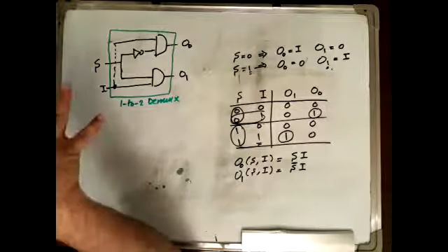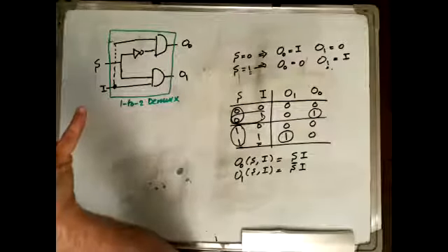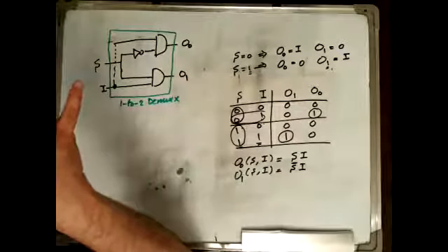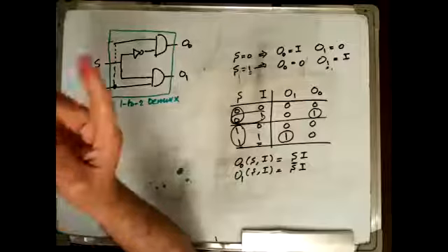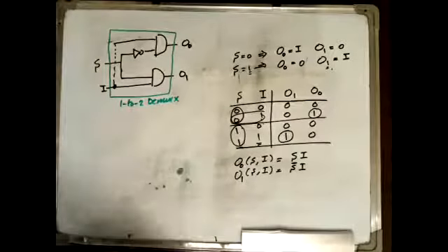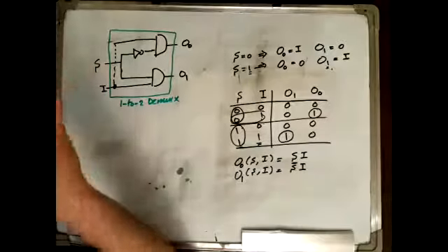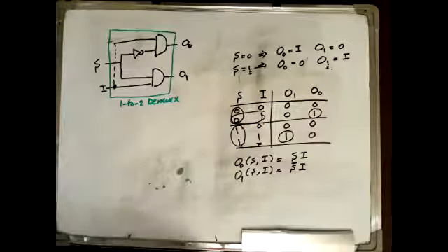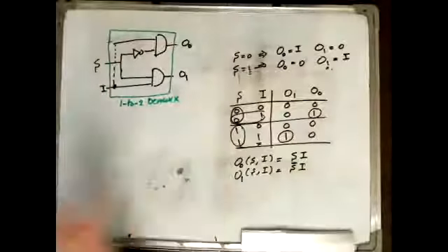Here comes the problem, because you will have 5 input variables: the input I and 4 selection lines to select one out of the 16 outputs. However, you don't need to go this way. In other words, to design bigger demultiplexers, can we design them in an easier way without using a truth table?